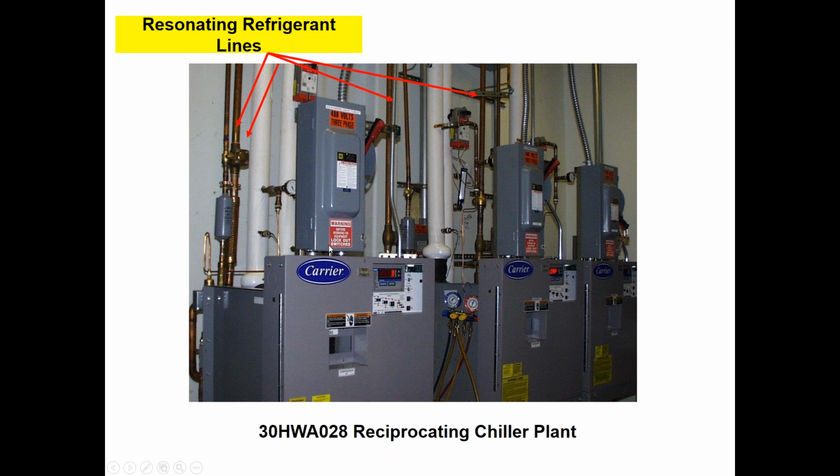Be conscious of what you're fastening the pipe to, and think about isolation. Now, we don't call out vibration eliminators on our equipment. If you want to use them on the Carrier equipment, Bryant equipment, that's okay. Just make sure they're full port. In other words, the ID is the same exact ID or larger than the pipe size. But you can use those. We just don't call it out in any of our manuals. So think about your mounting too, not just your equal spacing, your 3 or 4 foot spacing on the pipe, but think about the structure you're mounting it to.